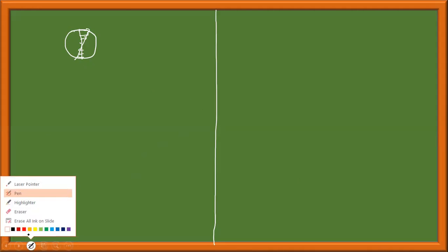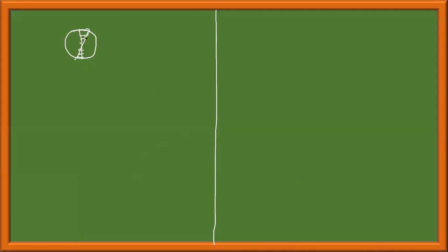When I consider a solid shaft like this, we know that the maximum shear stress is at the outer fiber, isn't it? This is where the maximum shear stress is. But this region of material is just a waste. There was no need of this material. The maximum stress is here. If I have the material at this region only, it's more than sufficient.